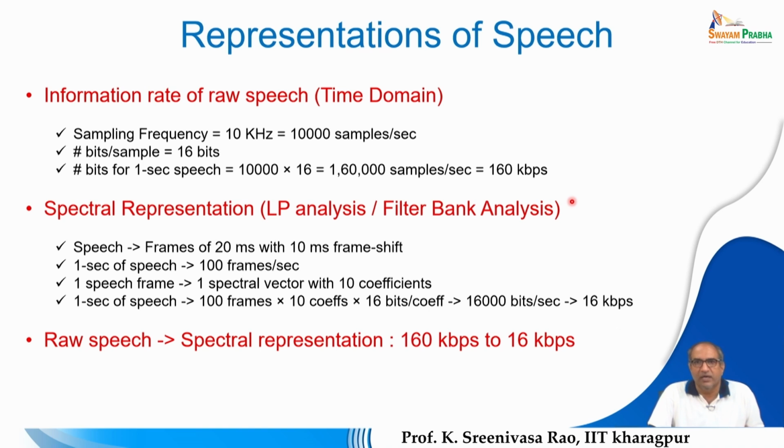Now in this topic we will discuss vector quantization. All of us are aware of what is meant by a vector: it consists of multiple values, and all those values are the components of the vector. For example, in spectral analysis, in filter bank analysis, speech is a wideband signal. If you pass it through a set of band pass filters, for example 16 band pass filters, we get 16 narrowband signals, and if we estimate the energy of these signals, we get an energy as the outcome from every narrowband filter.